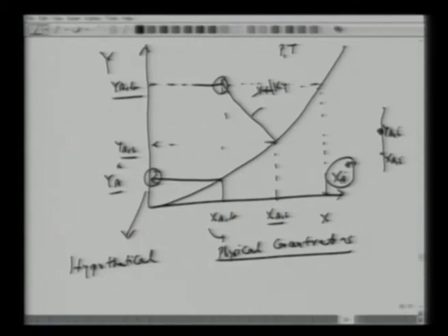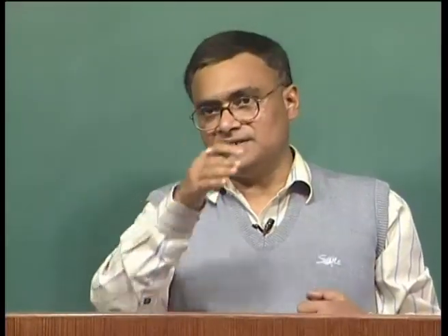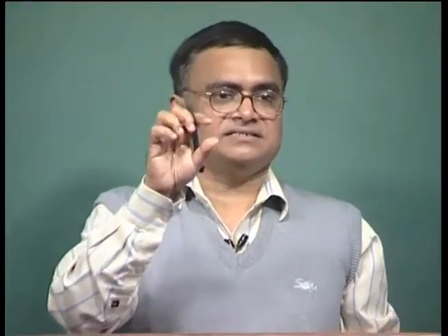if you go back and try to recall, we have a real system of gas and the liquid. Two are the bulk concentrations which are real. Two are the concentrations at the interface which are real. We can measure these two, we cannot measure these two. We have been asked to calculate diffusion flux. Thermodynamics says that given one concentration in one phase, we can calculate the other phase concentration under equilibrium. Okay, we are trying to avoid the measurements of XAI's and YAI's because these are not the major quantities.